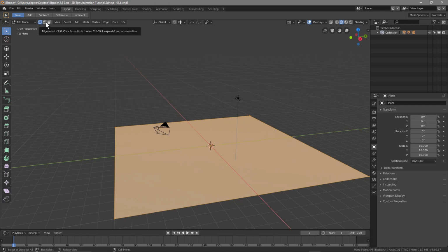And we want to manipulate this object by its edge. So we're going to click on here. Can you see edge? This middle option here. And we're going to click on this edge right here. And everything else will go black around the borders, and this edge will be white.